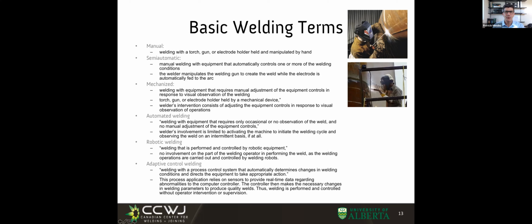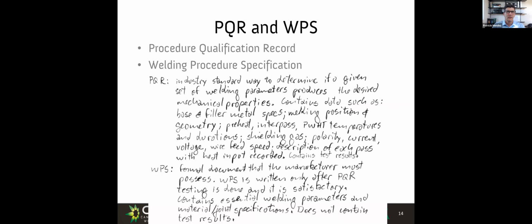Now, when I put my welding torch in one of those little bugs I discussed, for example, in the case of orbital welding, that is called mechanized. And now if the bug is somewhat intelligent, like for example a robot, now we start talking about automation and different levels: automated welding, robotic or adaptive. The American Welding Society went all too happy in defining all these, but once you start having feedback loops, we have a fairly advanced level of automation, whatever we call it. All of these we have in our lab, and I hope you'll come see them at some point.